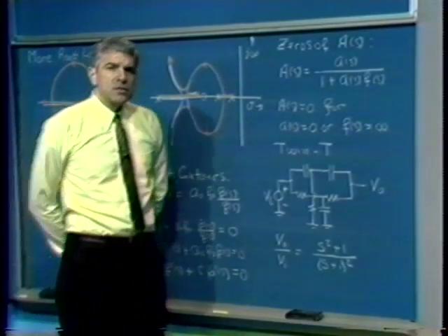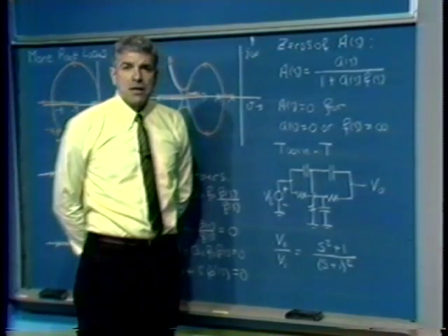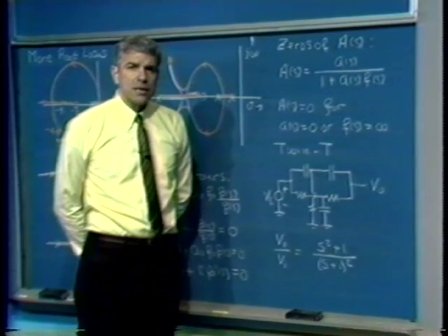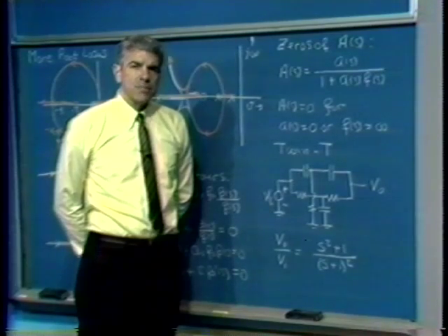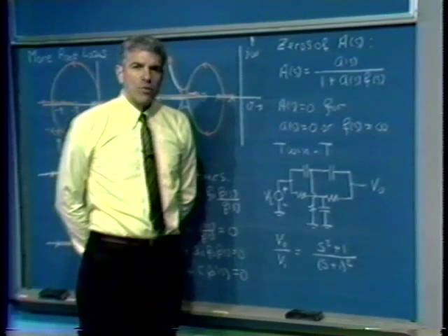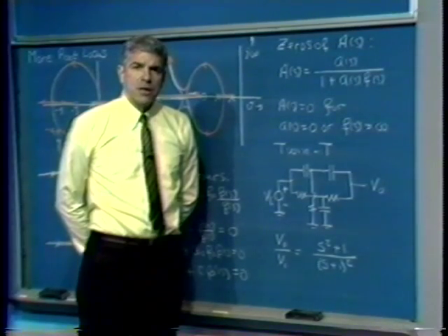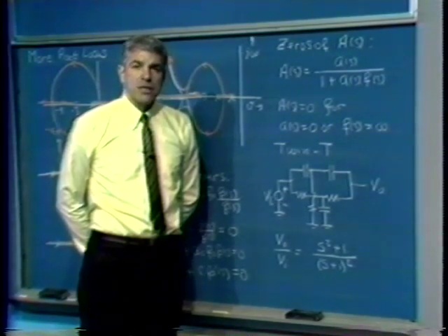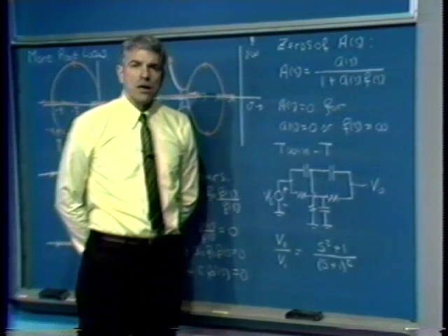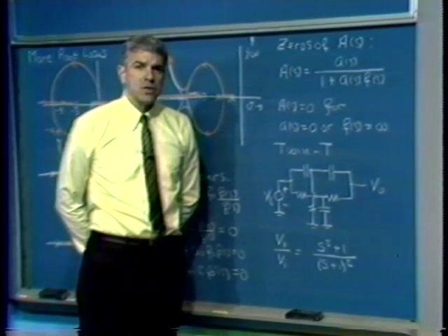While we can determine the stability of a feedback system, and in fact tell how close to instability we are, and those sorts of measures of relative stability, simply by looking at the closed loop pole locations, clearly an overall understanding of the response of a system requires the zero locations as well. And I'd like to do an example that shows the dramatically different performance we can get from a single system, in other words, a system that has the same pole locations depending on the location of its zeros.